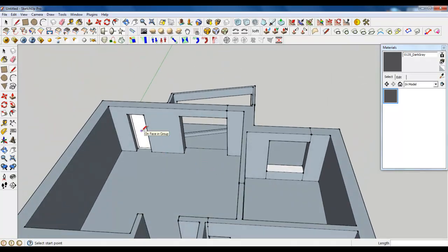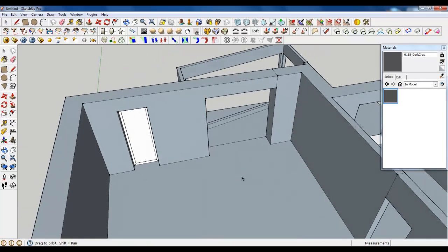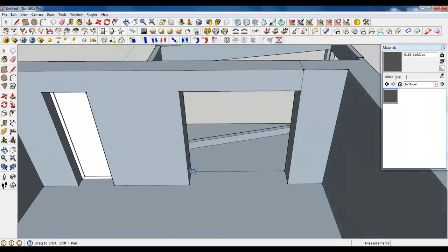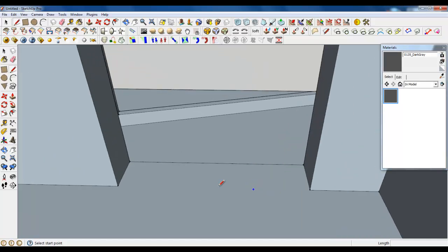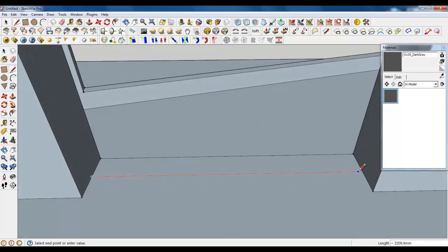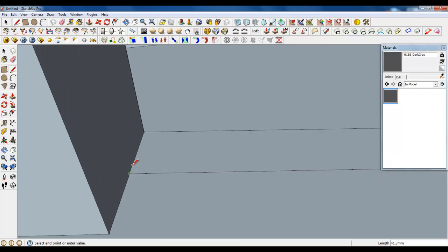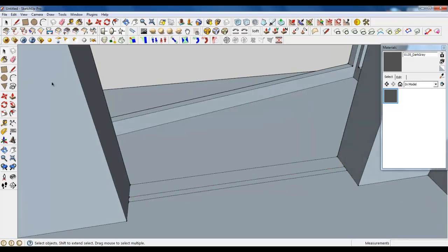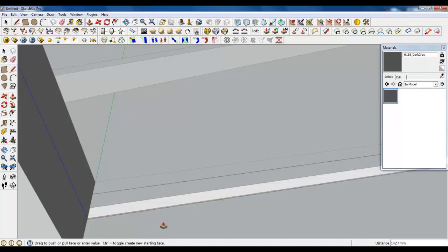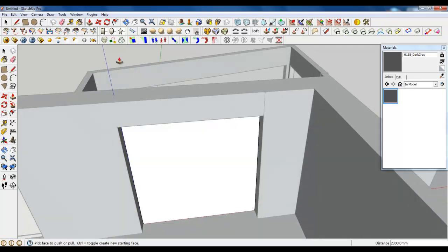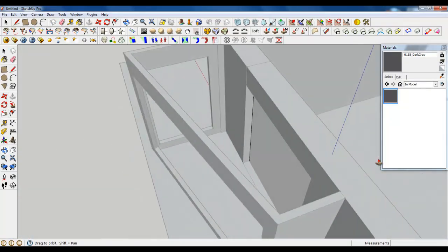In the same process we have created a dining room window. Well, it's time for the living room window, and the living room window will have a door, so I will show you how to make it. Okay, let's start, and the start is the same as we have done. Type 60, make a group, open and extrude. Use your offset 16 again and push pull.